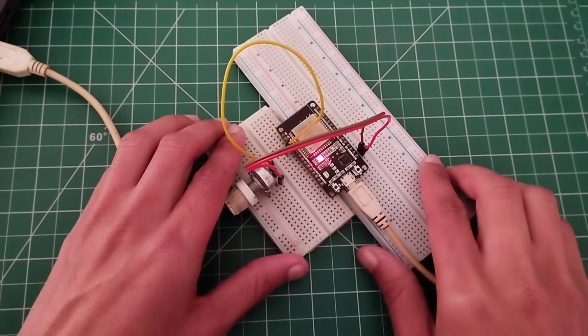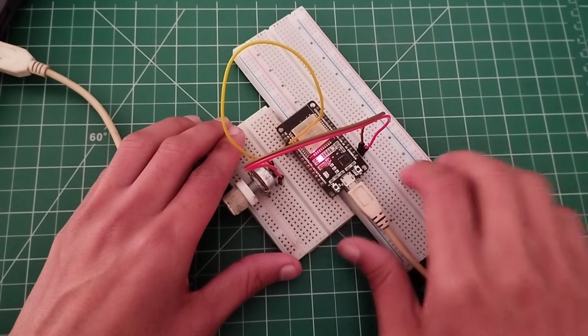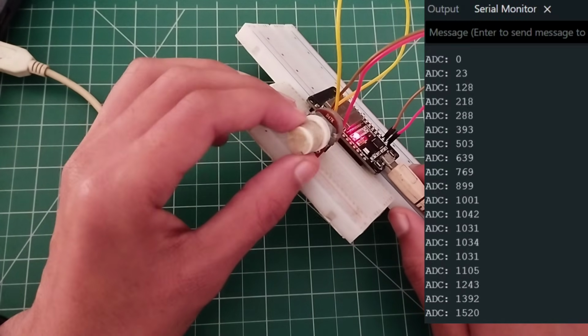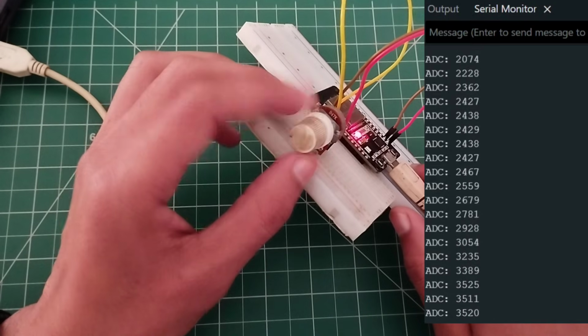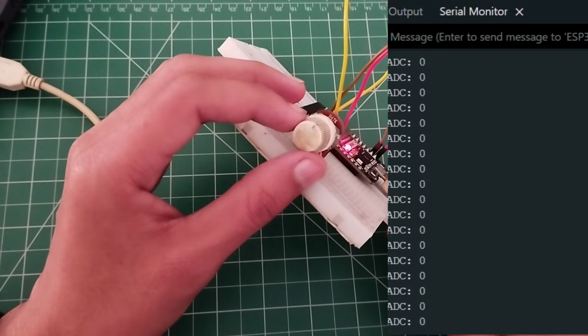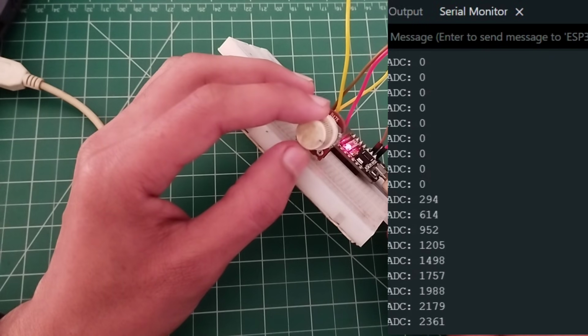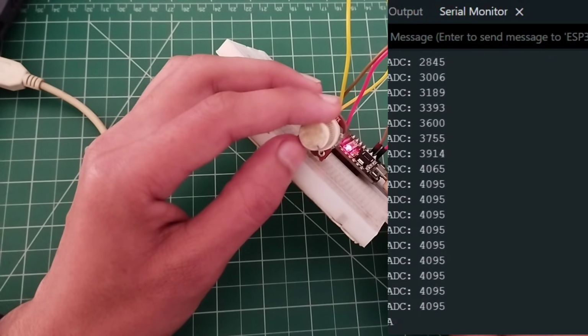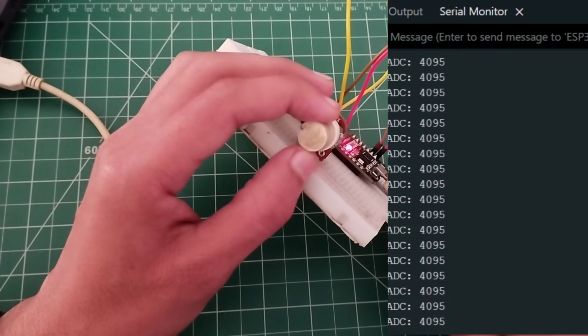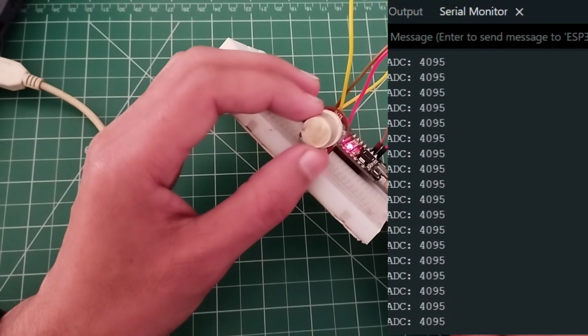Most beginners think that while using the ADC of ESP32, we would get values in the range 0 to 4095 for one complete rotation of this potentiometer, as you can see over your screens. And this is correct, there is no problem in that. But this time you will see that the value 4095 will be achieved somewhere here at this point. And if I rotate the knob further, you can see the value is not increasing. So I will explain why this is happening.